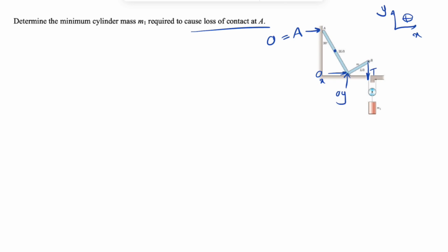And we're going to have the center of mass in each part of this beam. We know that the AO part is 2/3 of the L, the whole length. And since we have a homogeneous rod, that means that 2/3 of the weight would be in here, so mass times acceleration of gravity would be in there, and 1/3 in here.